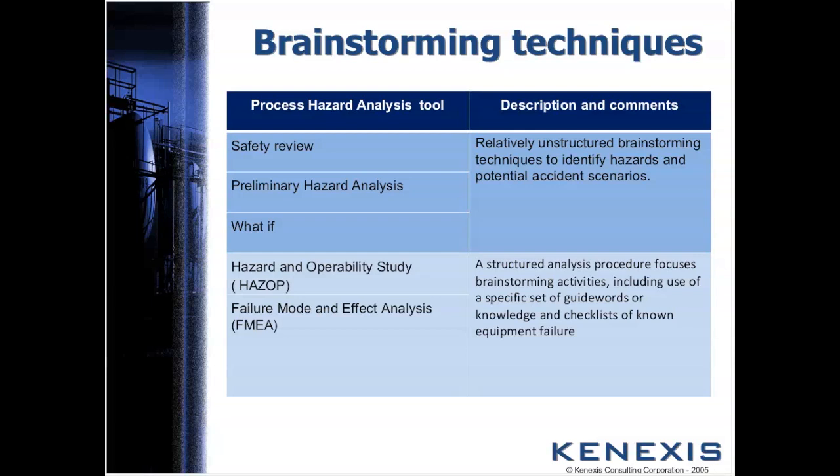So the what-if analysis encourages the hazard evaluation team to think about questions that begin with what if. What if I had the wrong material? What if the pump stops? What if a lightning storm comes over? Literally anything you can think of that's applicable to the process is available to ask in a what-if checklist. Typically questions are divided into specific areas of investigation like electrical safety or fire protection or personnel safety, and then we ask questions as a team and step through the process.